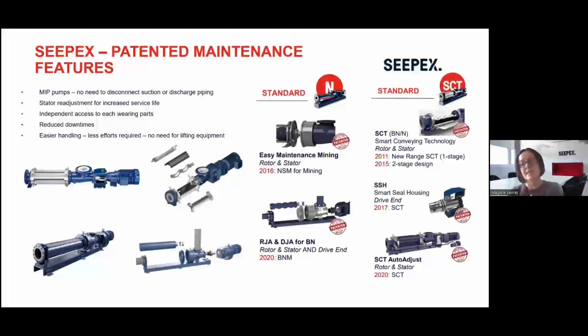That means that you can observe the flow rate decreasing from your control room, and you just push one button that will actually retighten some kinetic rings that are on our stator, and that will retighten the stator automatically without you being physically near the pump. So all these are patented features by SEEPEX, making sure we reduce downtimes, making sure the maintenance is easier and requiring less effort.